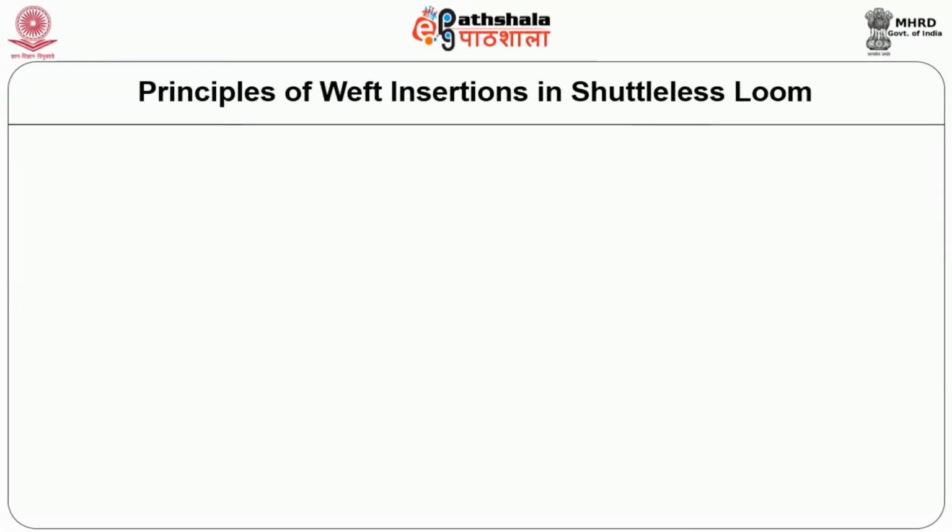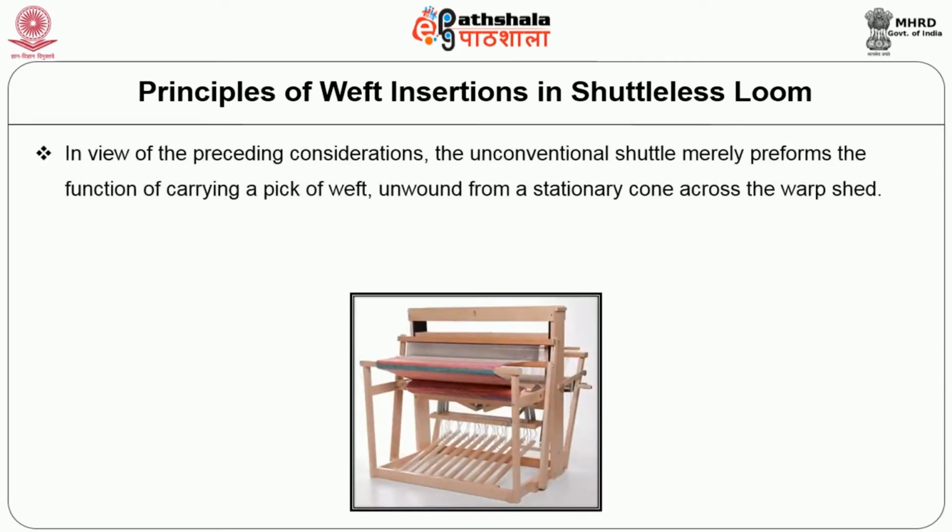And let us understand as to what is the principle used in weft insertion in shuttle-less looms. In view of the preceding considerations, the unconventional shuttle merely performs the function of carrying a pick of weft unwound from a stationary cone across the warp shed.